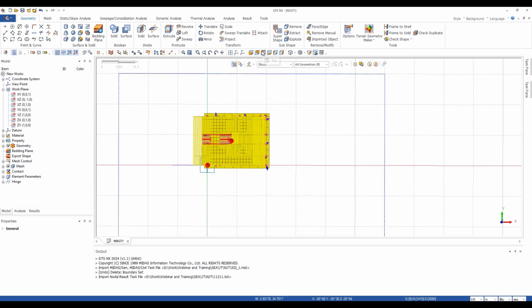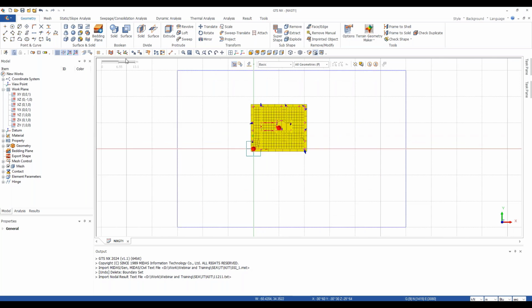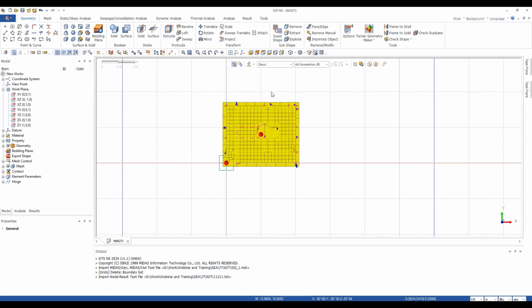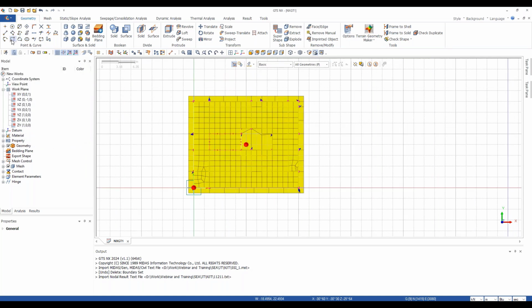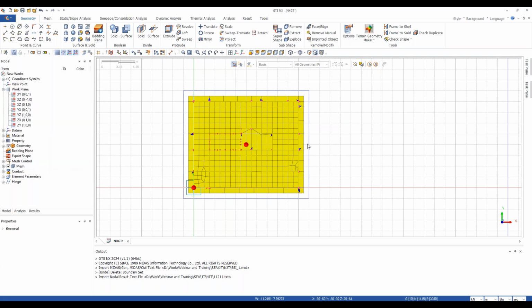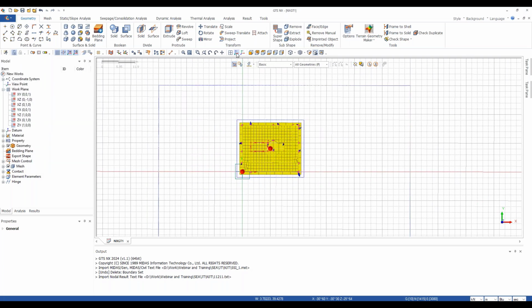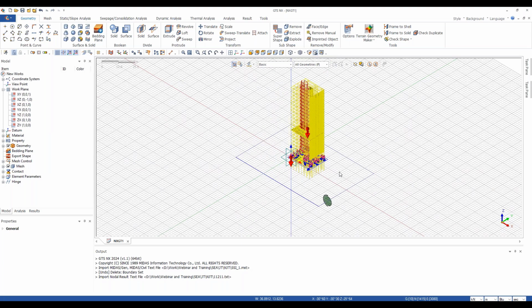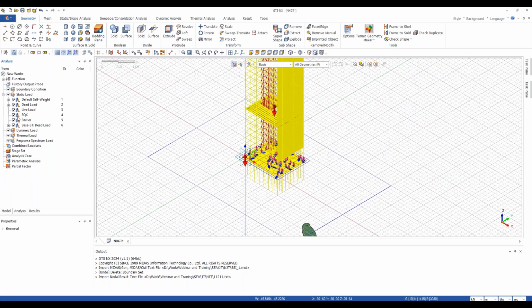And since we are doing the raft as well, we will create a cushion around the raft. For that, we will define a small boundary surrounding the raft element. So let me again choose 2 meter, and here I'll draw a rectangle around the raft basically. So this would be the cushioning area that would be given. And if you see, we have defined the geometries.